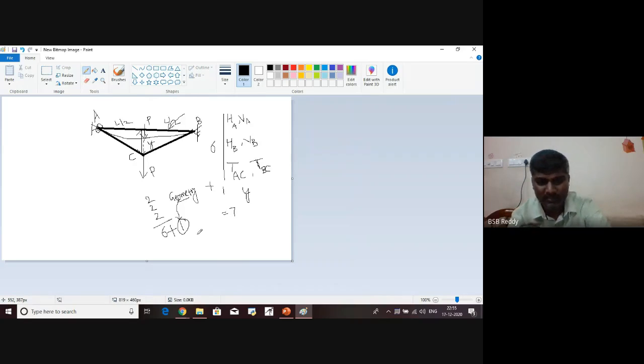This is the simplest of all the problems, a cable with one single point load, where you get 7 unknowns and need 7 equations, for which 6 equilibrium equations are possible plus 1 geometry relation, something like the length of the cable is so much, or else the y value will be given to you. Anything can be possible. That is how you are able to solve this one.